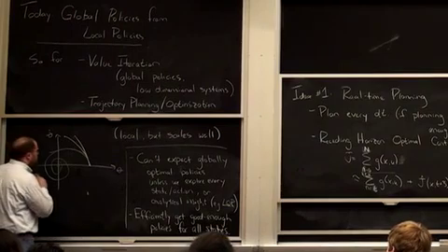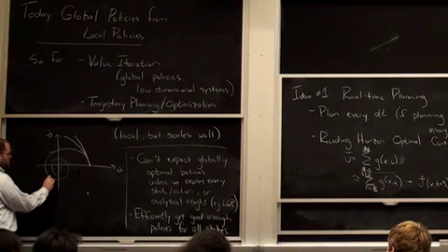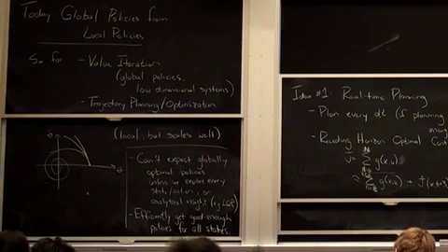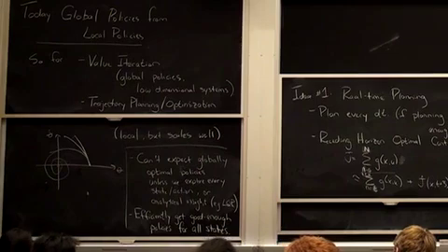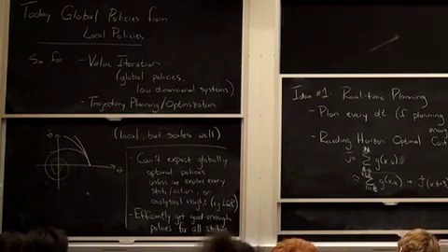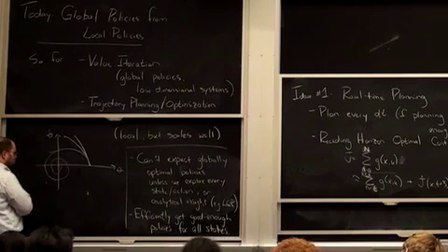So for instance, let's say I find myself off my trajectory somewhere over here. And I'm willing to say, my planner's fast enough, my controller's running at 100 hertz, right? And in 1/100th of a second, I can about solve an optimal control problem that's half a second in duration, let's say. That's a reasonable thing. Half a second along would put me here.